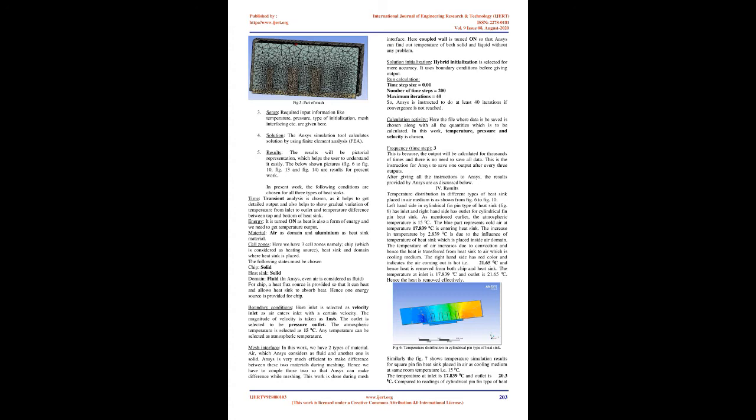The following states must be chosen. Chip, solid. Heat sink, solid. Domain, fluid; in Ansys, even air is considered as fluid. For the chip, a heat flux source is provided so that it can heat and allow the heatsink to absorb heat. Hence one energy source is provided for the chip.